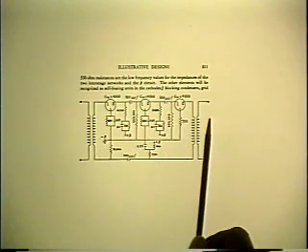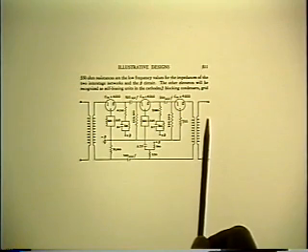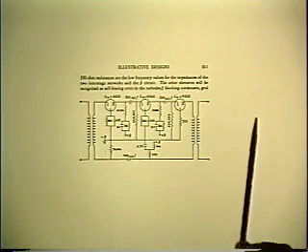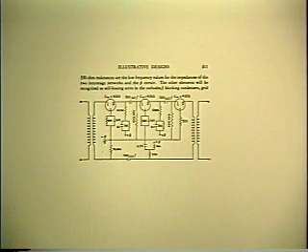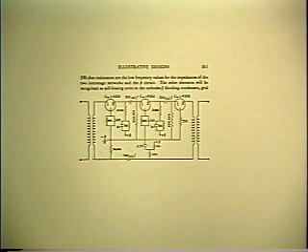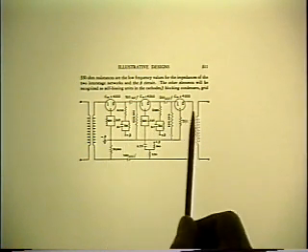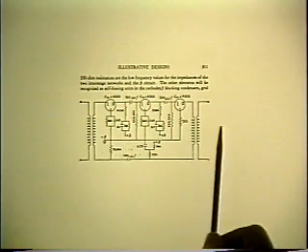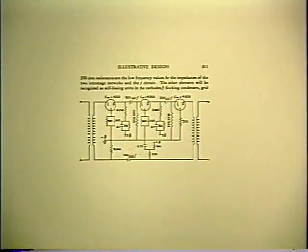And since all of this is to go into repeater amplifiers for transmission lines that require matched impedances, what better way to do it than with a whole lot of transformers? So that's why the examples are mostly of this type. And this was fine at the time, but of course we just don't design systems this way anymore. The whole philosophy is different. Because then you wanted to use as few active devices as possible, but you could use all the passive elements you wanted, including magnetics. Now the philosophy is exactly the opposite.